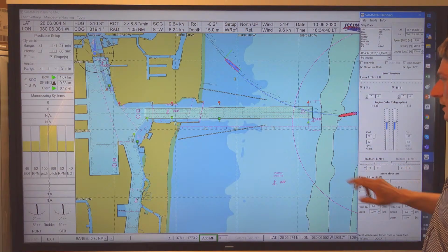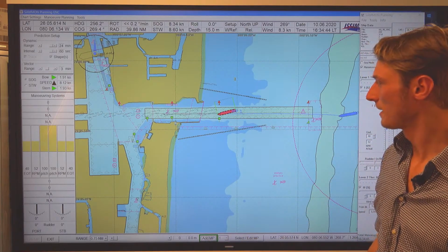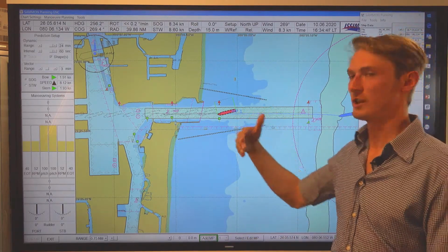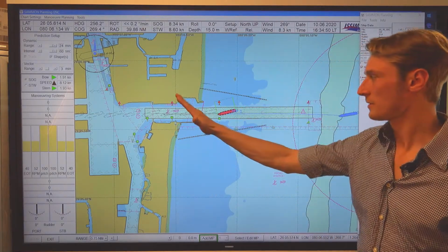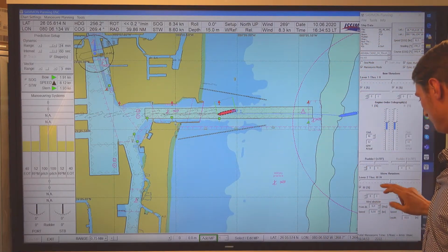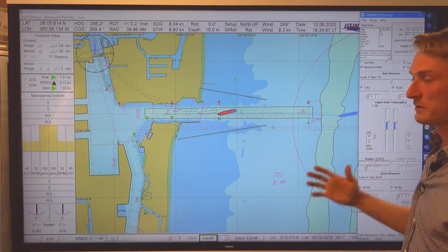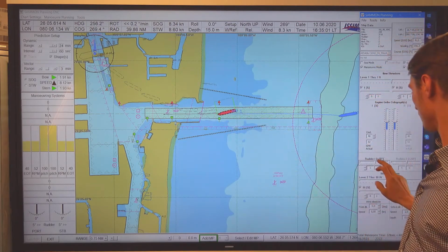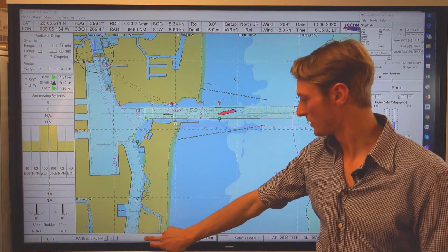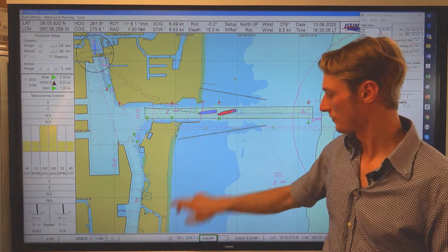First of all, over here I have to set a maneuver point, and from here on I'm allowed to change the maneuver to continue my plan. So I give a rudder command to starboard. 5 degrees, 10 degrees, it's a good question. Let's start with the 5 degrees. And I move further inside. So once the ship has entered the breakwater, basically the bow,